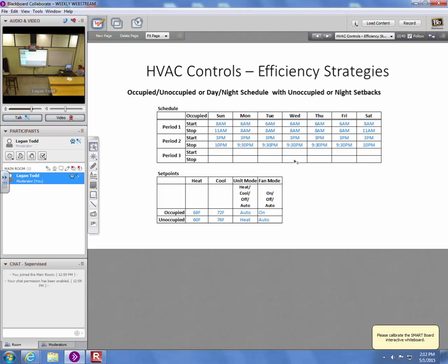And so if you had a 7-day programmable thermostat, some of them even will have, within each day, multiple periods. So this would be kind of at the high end of flexibility. You can have a different occupied, unoccupied period for each day of the week. And then within each day, you can have a period 1, which is like everybody's getting up, having breakfast, getting ready for school or work. And then period 2 where everybody's at work, and then period 3 where everybody's come home from school or work and they're having dinner and headed to bed, and then maybe period 4 is bedtime through the night.